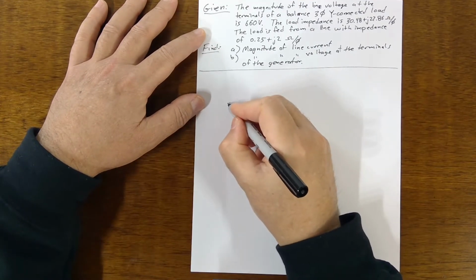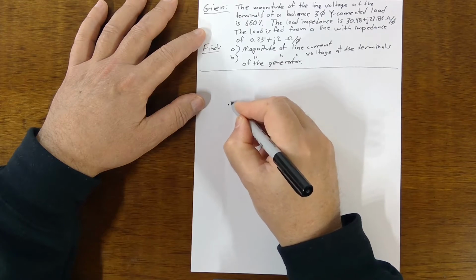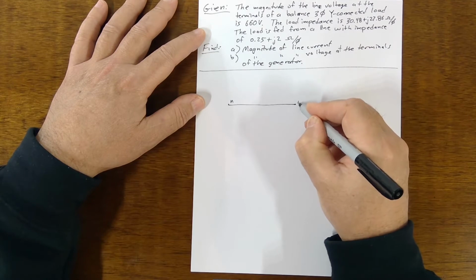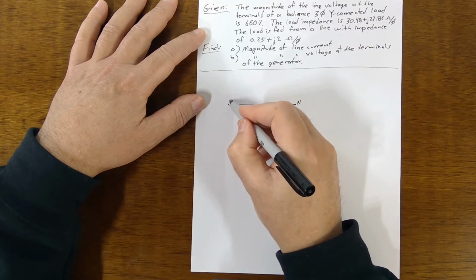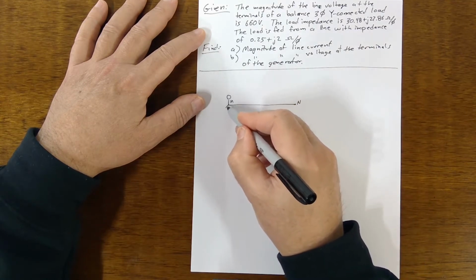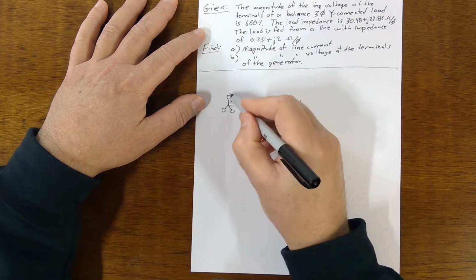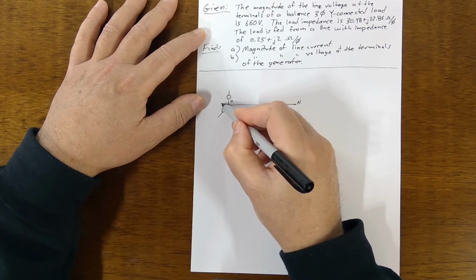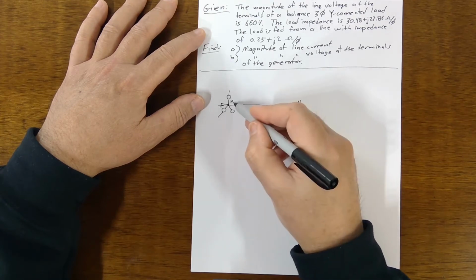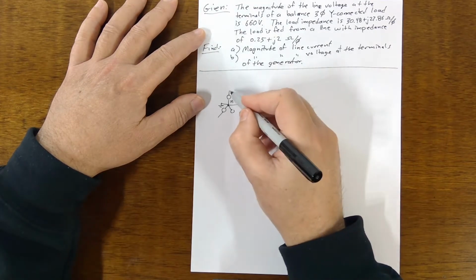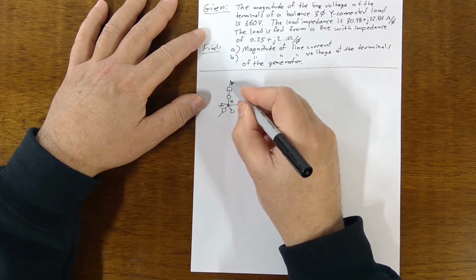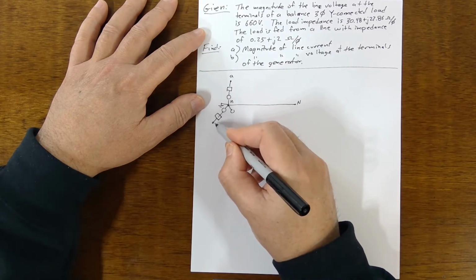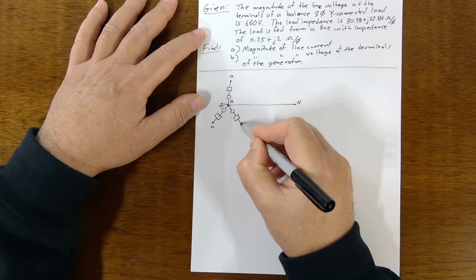So we've got a three-phase Y-connected load and a generator. The generator is modeled by three voltage sources, okay, at little terminal N, which is grounded. So that's a terminal, right? The neutral, which is a ground, is a terminal. And then there's an internal impedance going out to a terminal A, and then there's an internal impedance and terminal B, and then another one, and then C.